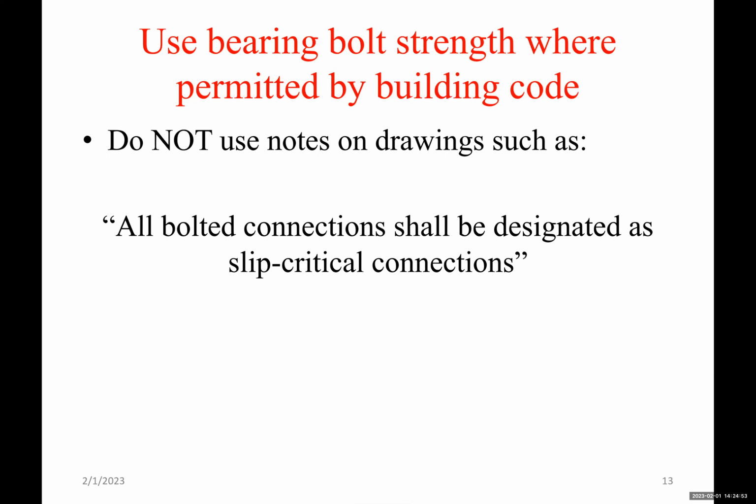Okay, so slip critical connections need surface preparation. They rely on a coefficient of friction. We have some values in the codes. You know, there are different values for different surfaces. This has to be checked, this has to be guaranteed.